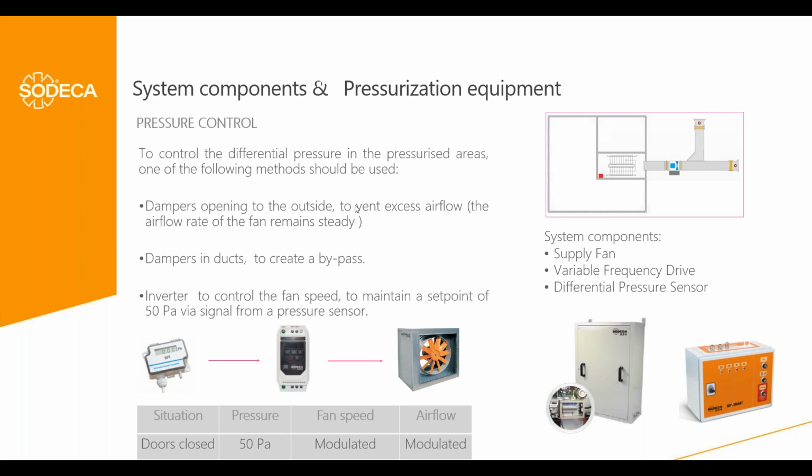Okay, so this damper has to be calculated for this difference between the airflow in the door open condition and airflow in the door closed condition. One of the problems of that system is that the airflow in the door open condition will be the maximum airflow of the fan. But the airflow in the door closed condition is something that we calculate, and I can assure you that will never be the one that you will have in the real building, because you will have more or less leakage in the building.